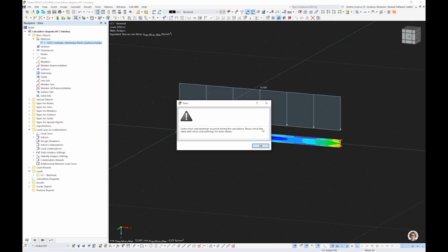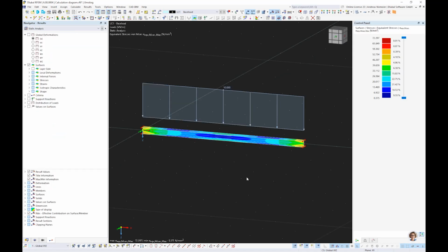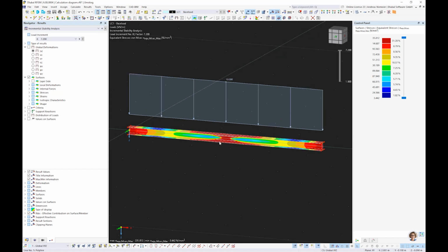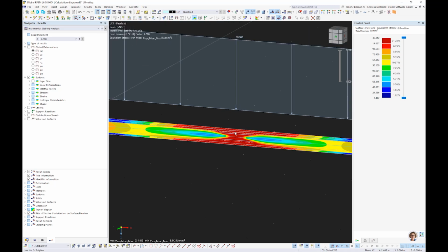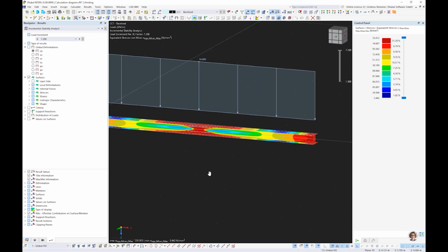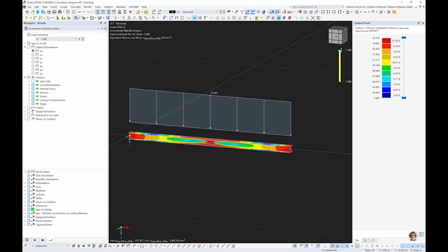So this is connected to the stability add-on, only a robust function in this case. But what is now the change? In this view, nothing. Of course, we have to change here to the incremental method. And now we get a really interesting picture. Red in the middle, red on the right and left side. It seems like a plastic bending moment, plastic load distribution. The same here. What is also new? You have here such a scaling factor. Here you can say this is load factor 7.2, this is load factor 1, which we saw before. Maybe you can change directly here in between.